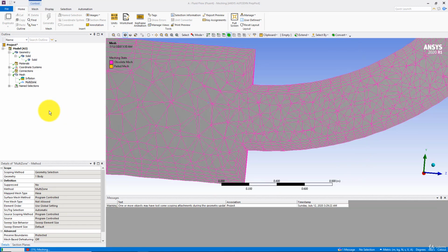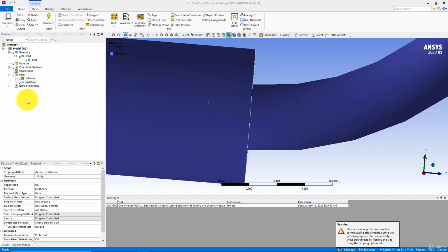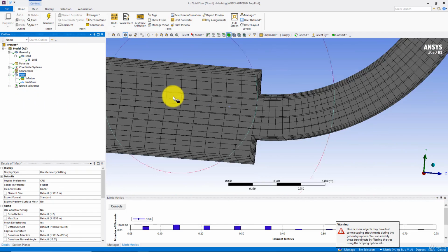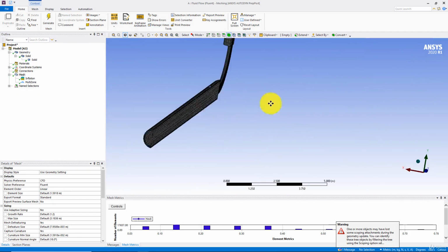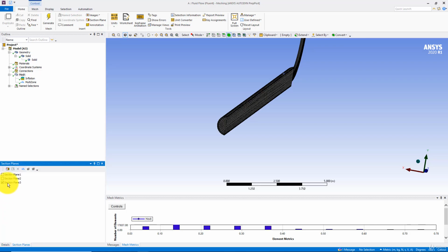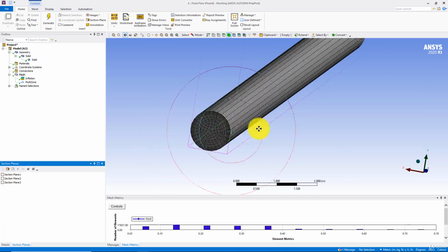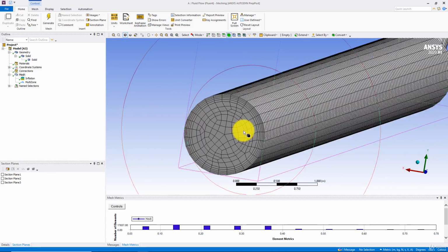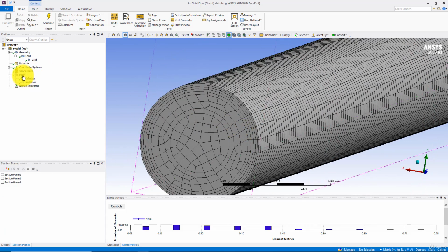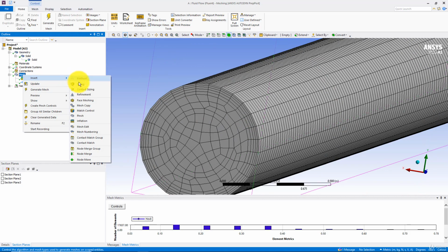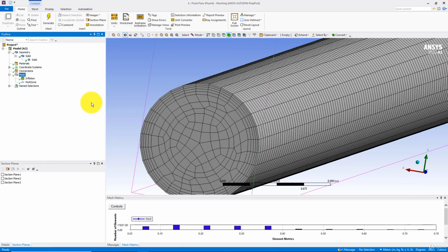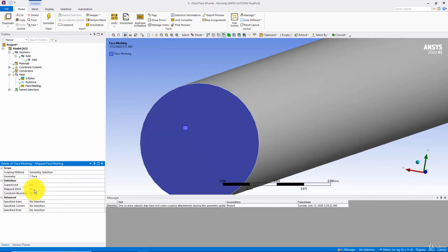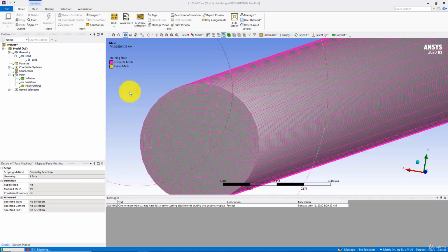And I recommend that you try all these things inside the ANSYS Workbench and see how they behave. And you can see now we are able to create full hexa meshing, almost full hexa meshing, without much effort. And if I try to put the face meshing here on this face as a map mesh, yes. And then I can try and see what will happen here.